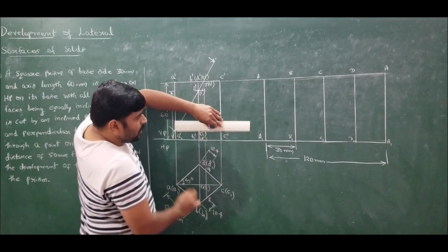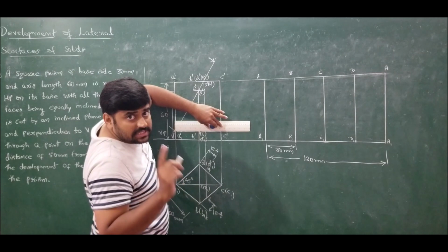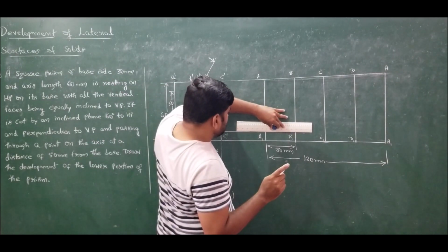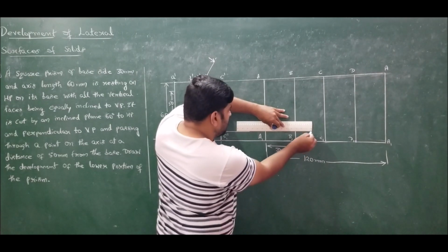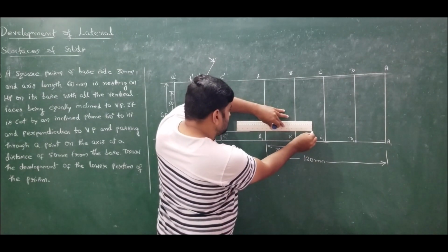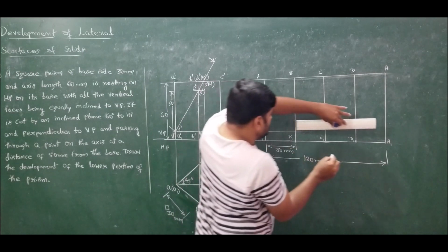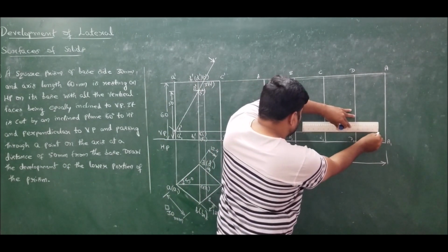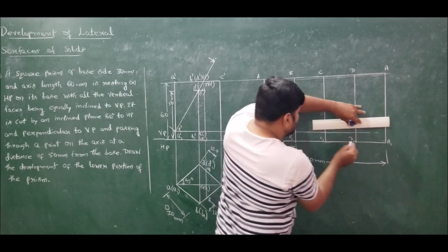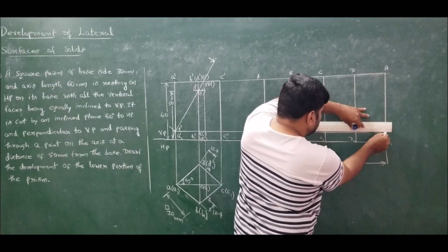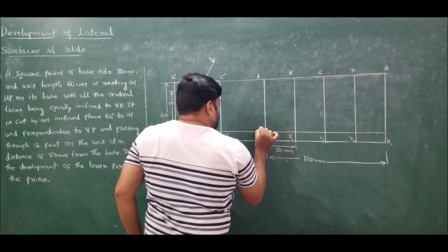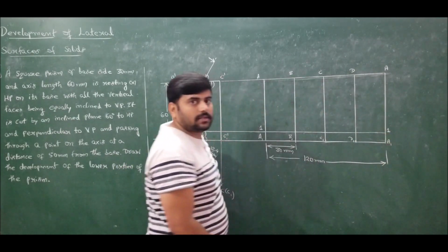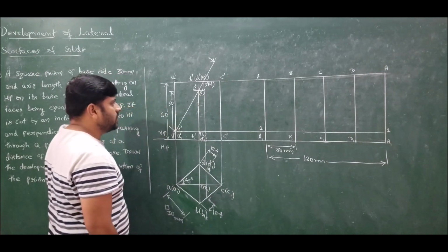This procedure can be employed only for prisms, cylinders, and cubes, and also objects of similar type for which the longer edges or vertical faces are parallel to the axis. So we have the longer edge A at the beginning and also at the ending. Hence extend it till the end point and mark it as 1. And this is also 1. Done.